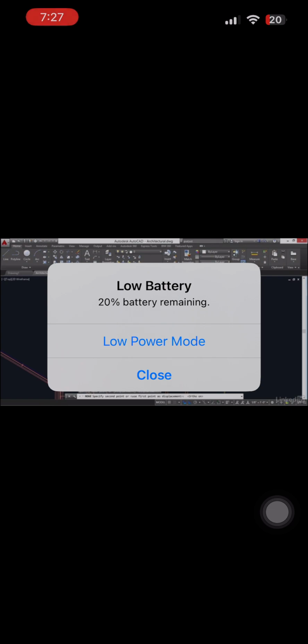I'll move the cursor up relative to the point A or base point that I selected. And the tooltip is telling me how far I'm moving it. I don't recommend that you carefully move this until it says 4 feet, because you'll probably miss it by a little bit. If you want to move it exactly 4 feet, all you have to do is type 4 feet. The feet symbol is the apostrophe, which is right next to the Enter key on most keyboards. So I typed 4 foot, enter, and I moved the chair up exactly 4 feet vertically.